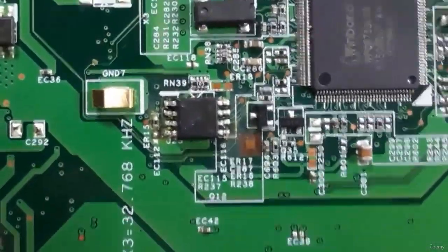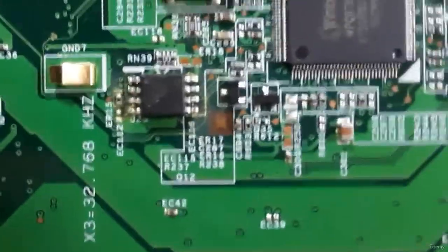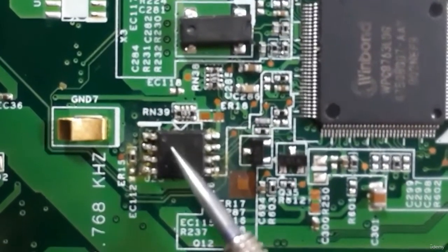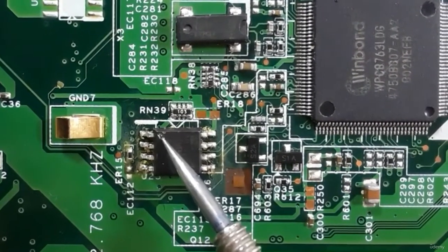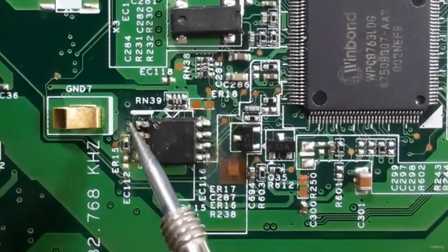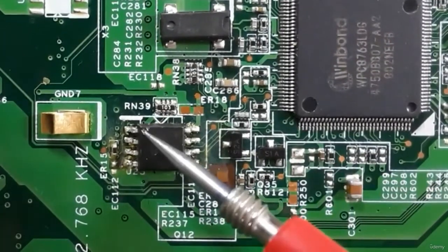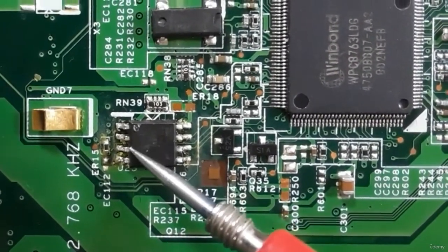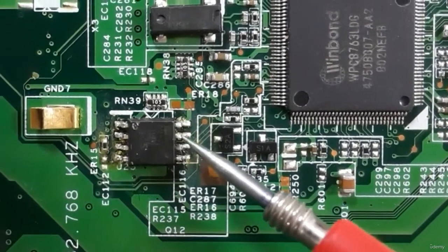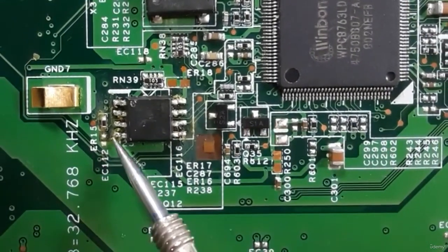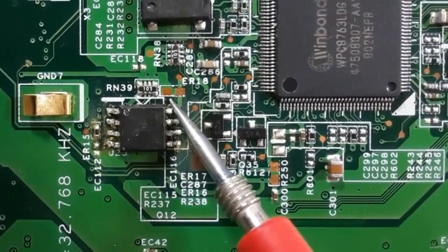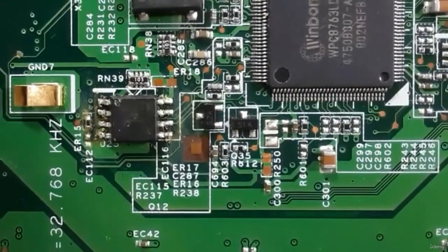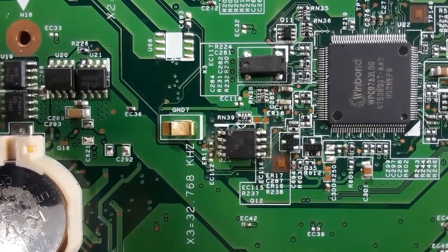Okay, so this is the BIOS with 8 pins, as you can see. Always the pin number 1 is marked with a hole here, or as you can see, this mark means this is the pin number 1, 2, 3, 4, 5, 6, 7, and 8. Always the pin number 4 of the BIOS is connected to the ground, and the pin number 8 is connected to the VCC, which is equal to 3.3 volts.